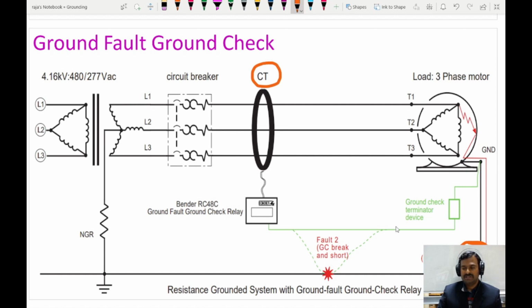And the second function is to monitor the healthy condition of this conductor. This is achieved by giving a small DC signal from here. This DC signal will be sent through this, and if the path is closed, then the resistance would be very low. If the path is broken, then the resistance would be very high, and this change from low to high resistance will be compared, and this will open, or give a signal for the operator, or whoever is the responsible person for removing the fault.